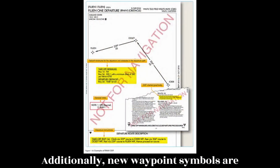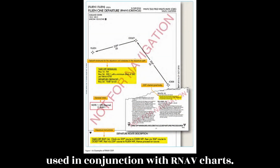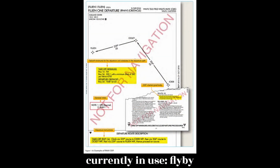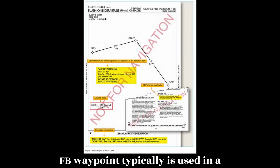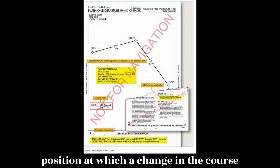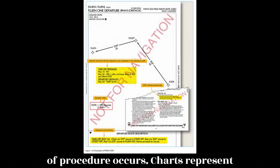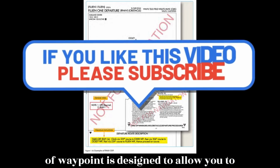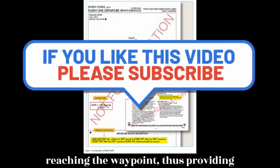Additionally, new waypoint symbols are used in conjunction with RNAV charts. There are two types of waypoints currently in use: flyby, FB, and flyover, FO. A FB waypoint typically is used in a position at which a change in the course of procedure occurs. Charts represent them with four-pointed stars. This type of waypoint is designed to allow you to anticipate and begin your turn prior to reaching the waypoint,